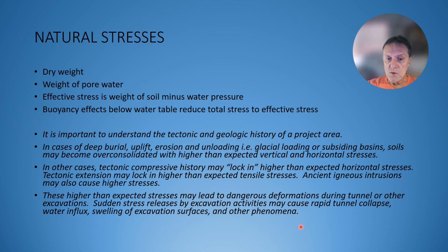These can lead to dangerous deformations. Let's say you have an overstressed, over-consolidated material and you want to dig a tunnel through it. Well, you're digging a hole through a very compacted, consolidated mass, and what you're doing is relieving ancient stresses. You're causing these stresses now to go to that region of low pressure that you've created by digging a tunnel, so you can have deformation of tunnel walls, compression into the tunnel space, which can lead to dangerous conditions like tunnel failure, rock burst, etc.